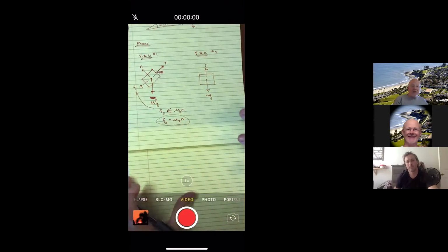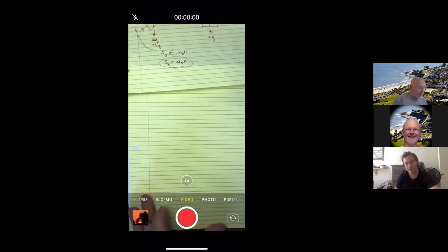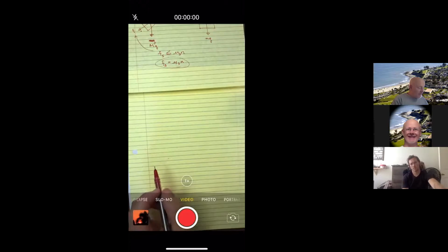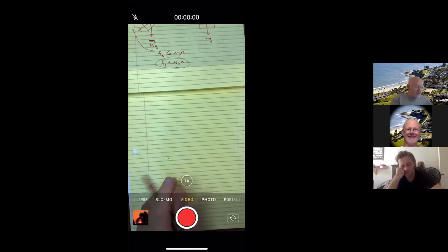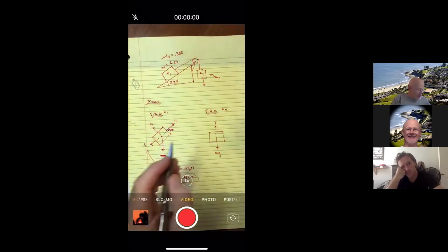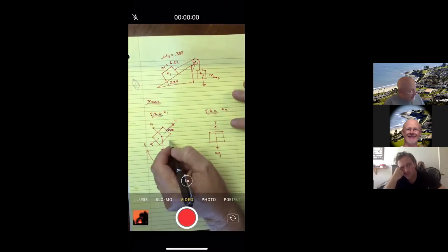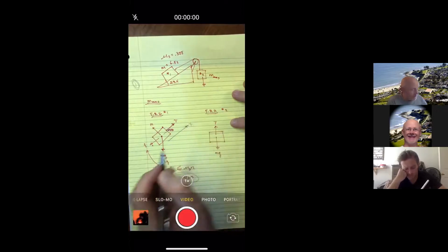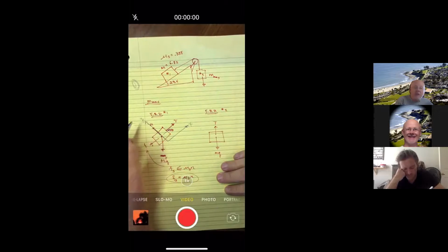I think what you're saying then is what I call step number 3. Then step number 3 here is like it says, okay, let's go ahead now and actually write out the equations. And to do that, this is what you were saying, you need a grid. You need an X and a Y axis. Mm-hmm. And so coming back to this free body diagram, and maybe in blue, I like to call the x-axis the direction that the two are moving when you have something like this. So what you're saying here is this one is accelerating up. Okay? So let's call that the x-axis, which then by default makes the y-axis perpendicular.